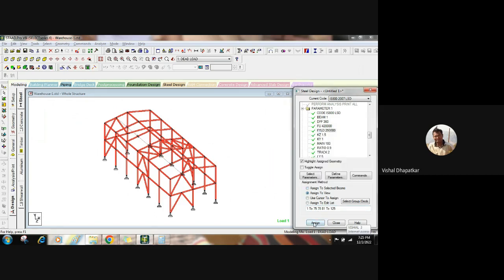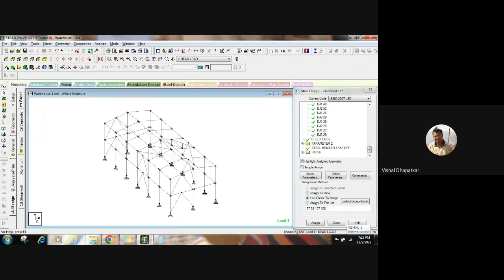Pretty much 10 each time. KY, KZ we don't know for those members. Ratio 0.9. Track. LY, LZ, there is no change. Okay, so just simply run it again.